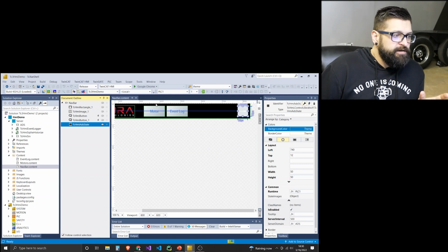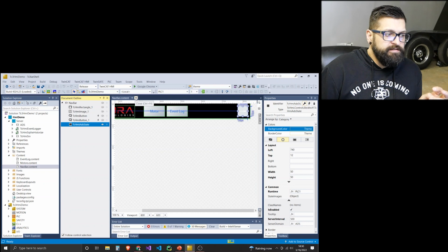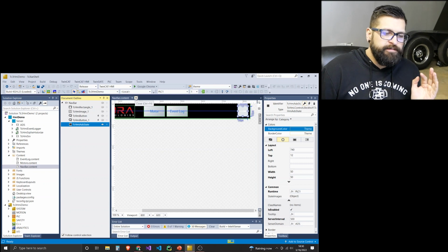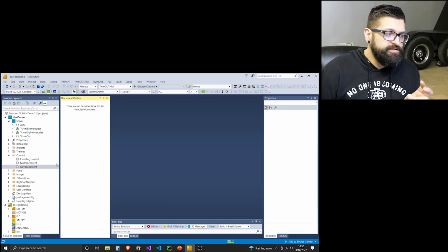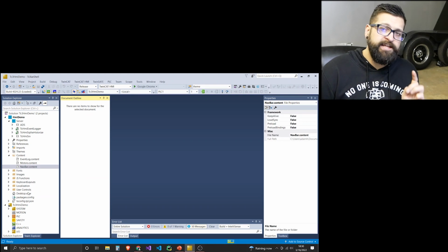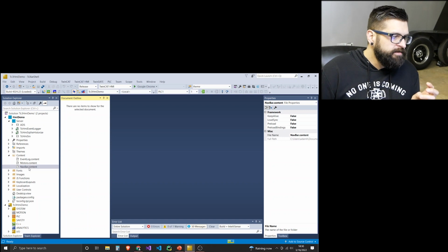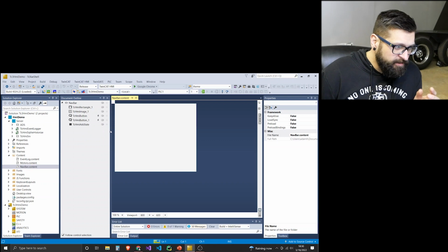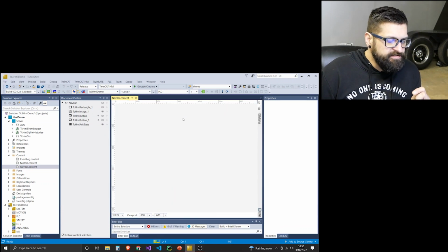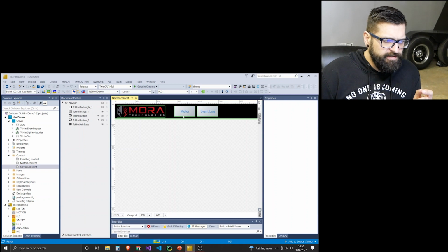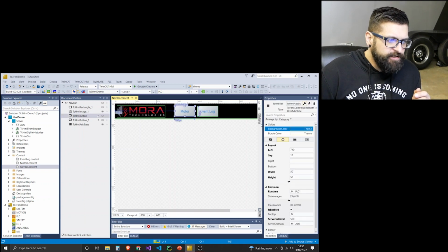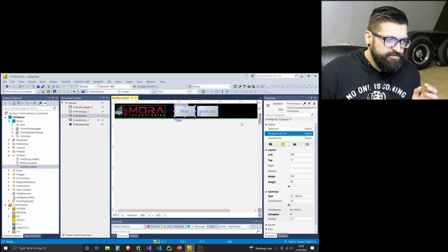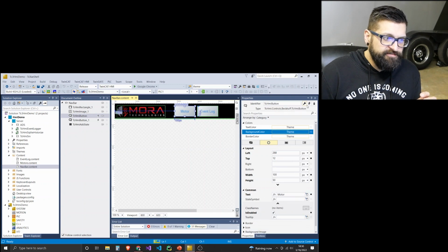So that's the primary approach that we're going to use to developing a view. We're gonna partition up a view into regions, and then we're going to dynamically change the content of those regions based on interaction with buttons or however you want to do it. So I'll go back to this navbar and I'll show you that what we're really doing is when an operator clicks on the motor button, if we go to our events, because if we were doing this straight up web development, we would add an event listener for on click or on touch or on pressed or whatever.